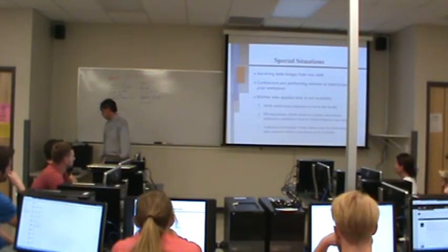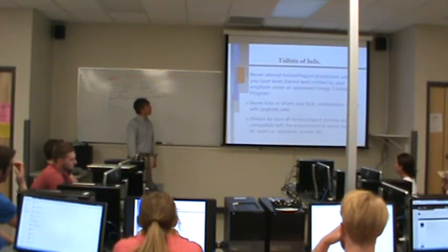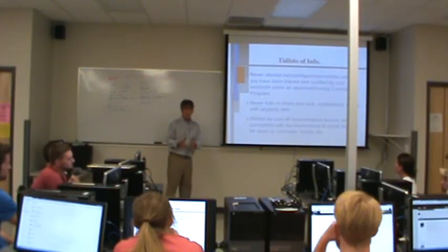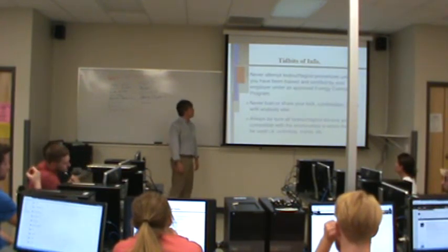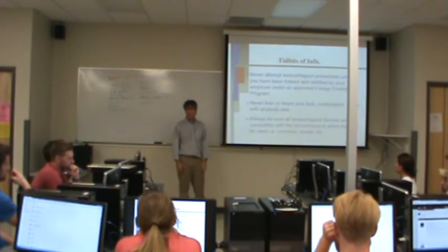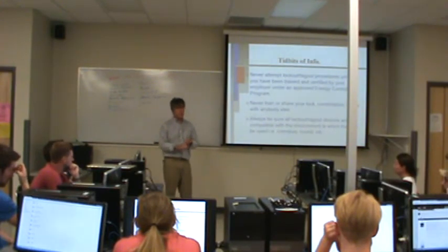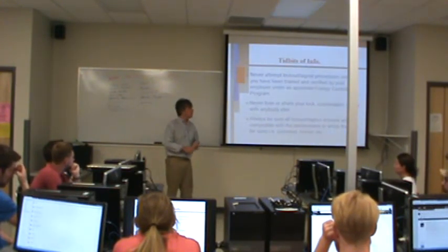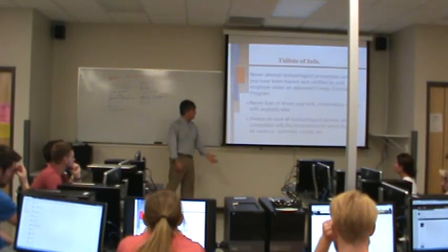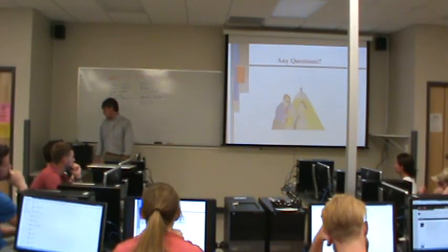Okay? All right. Now, a little bit of information. Don't try lockout tagout unless you've been trained on the procedures at the particular facility where you work. Okay, that's a big no. Never loan or share your lock, key, or combination with anybody else. Why? Because that's there for your safety. A lock and key is cheap. Human life is expensive. Always be sure all lockout devices are compatible with the environment that they'll be used in. You don't want your lock to rust off. Any questions?